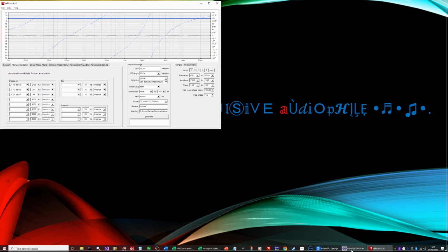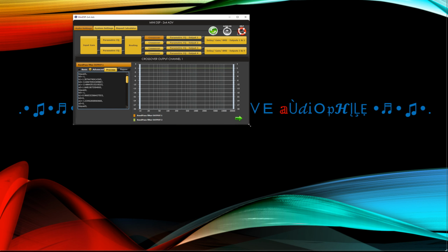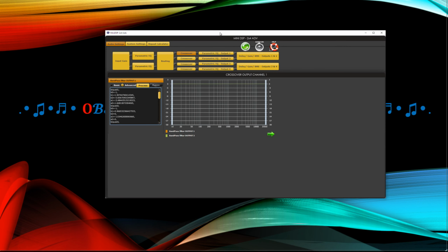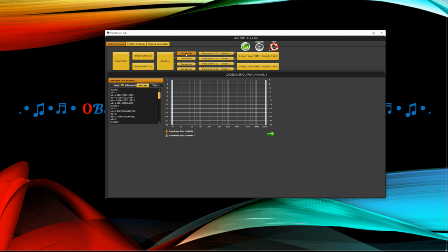Now let's go to miniDSP. For example, my miniDSP 2x4 Balanced, the very primitive old miniDSP, has 5 biquads here for parametric equalization and another 5 here. And these are the crossovers, but the crossover filters in fact have capacity to accept 8 biquad filters. You have 5 here and 5 here, 10, and 8 here, 18 separate all-pass filters or biquads you can enter in just one channel. Even in the oldest, simplest form of miniDSP, even for the lowest frequencies, you can add corrections.